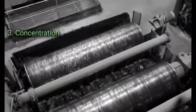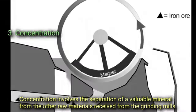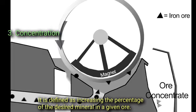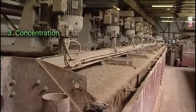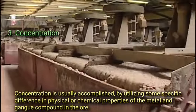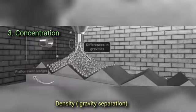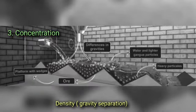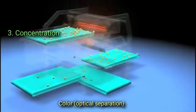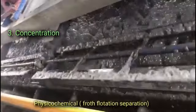3. Concentration. Concentration involves the separation of a valuable mineral from other raw materials received from the grinding mills. It is defined as increasing the percentage of the desired mineral in a given ore. Concentration is usually accomplished by utilizing some specific difference in physical or chemical properties of the metal and gangue compound in the ore. These properties can be density, gravity separation, electric conductivity, electrostatic separation, color, optical separation, magnetic separation, and physiochemical, froth flotation separation.